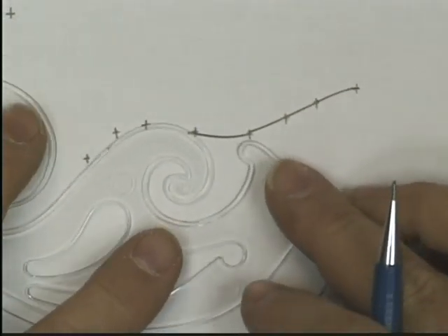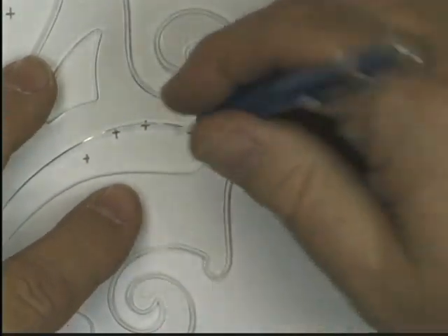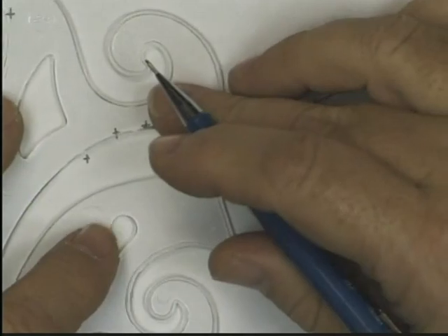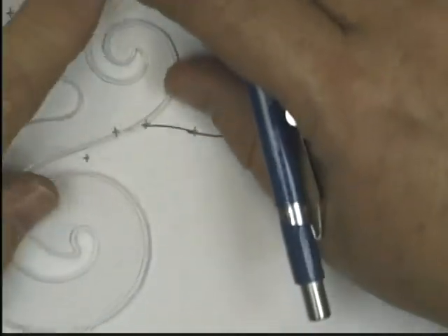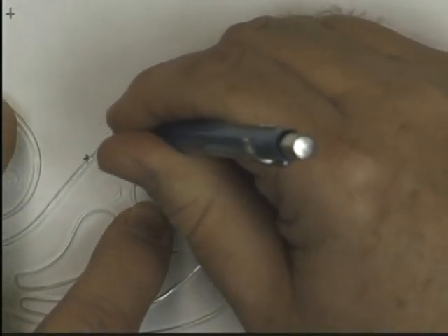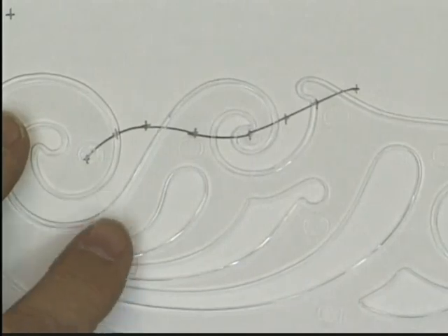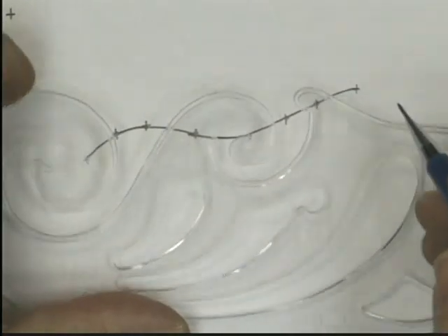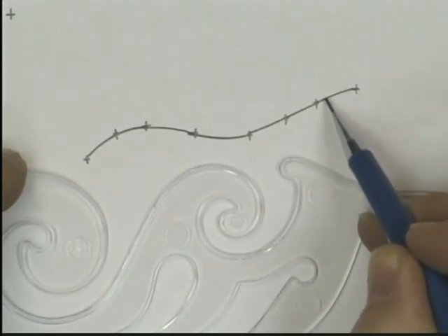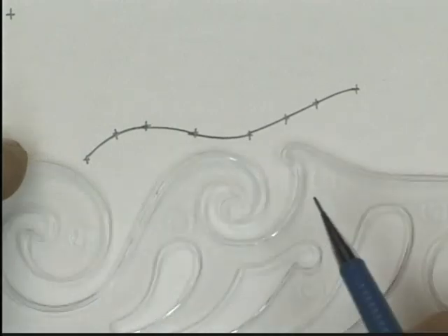And if you have the full set of curves, you'll always be able to find a bunch of matches, matching connecting dots. Okay, once more here, and I think I get it curved. Whoops, I need just a little more curve than that. I'll turn this over again and find the place where I can line up the last dots. So irregular curves are used, and there are lots of different sizes and shapes, and you have to be patient. You find a place on the curve where you can match up at least 3 dots, and then you draw 1 less than the number of dots you've matched, and you continue that process until you've played follow the dots using the irregular curve.